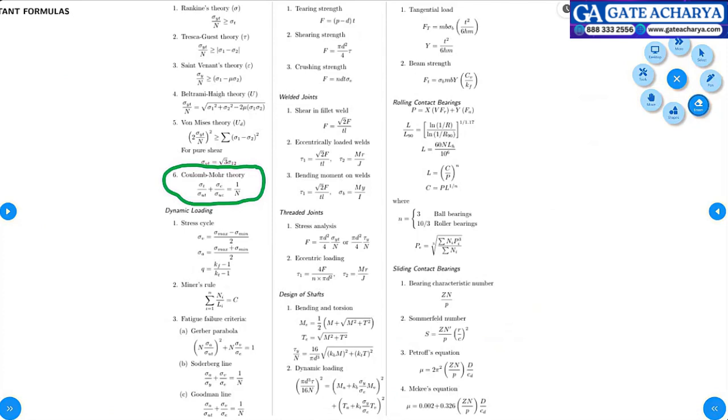Then why does cast iron have a higher compressive strength? See, steel material, the more and more you pull, atoms will move away from each other. So it's more ductile in nature. But cast iron is not so. You cannot easily pull that one. It's something like glass, you assume. So if you drop cast iron, it will get shattered into pieces. That is the failure mechanism. So it will take only compressive loads. It will not allow ductile loads.